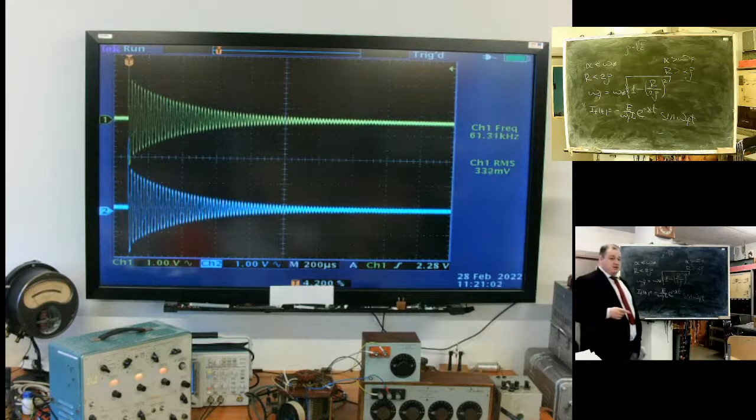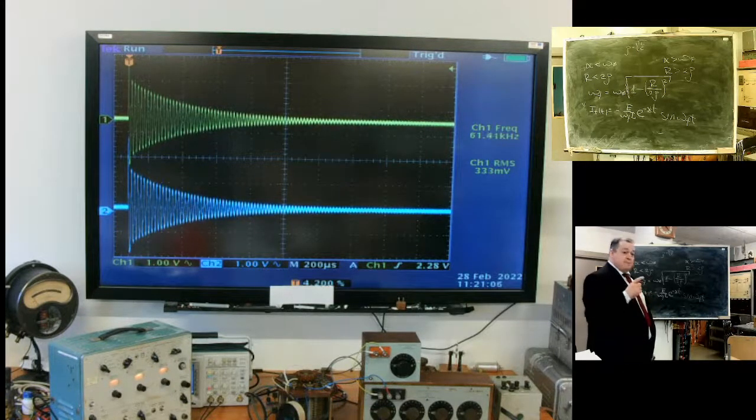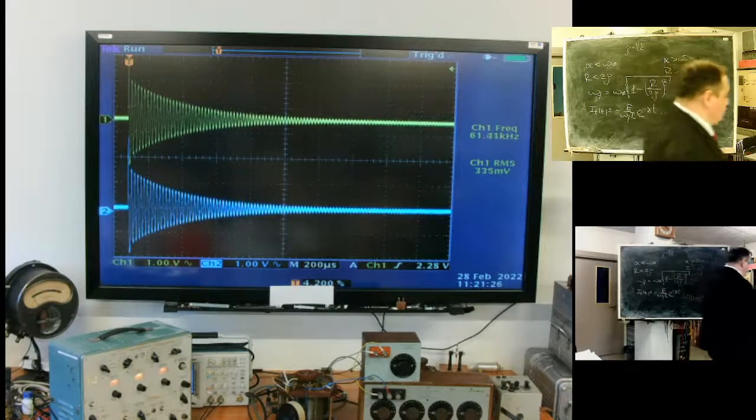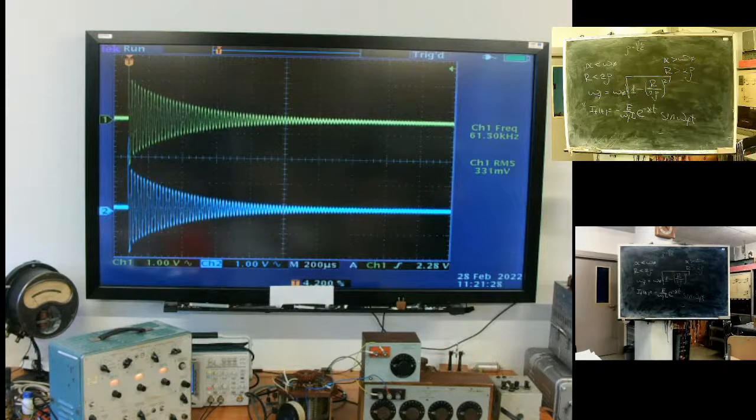The problem is that the frequency of such oscillation depends on the overall circuit resistance, including resistance at the fault place. So if the fault is not complete, so it is a transient resistance at the fault place, frequency changes and fault location fails.